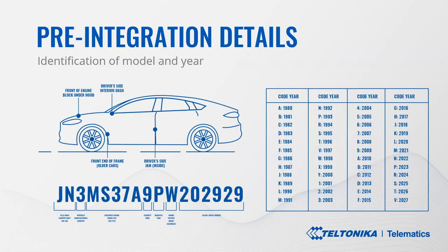So basically, identification of the vehicle can be made according to the VIN number. Any standard vehicle database search platform can provide you information just on manufacturer and model. However, usually details such as make year and options will have a cost. So as an alternative, if you have already determined the VIN number, you can also refer to the presented table to identify the manufacture year on your end.